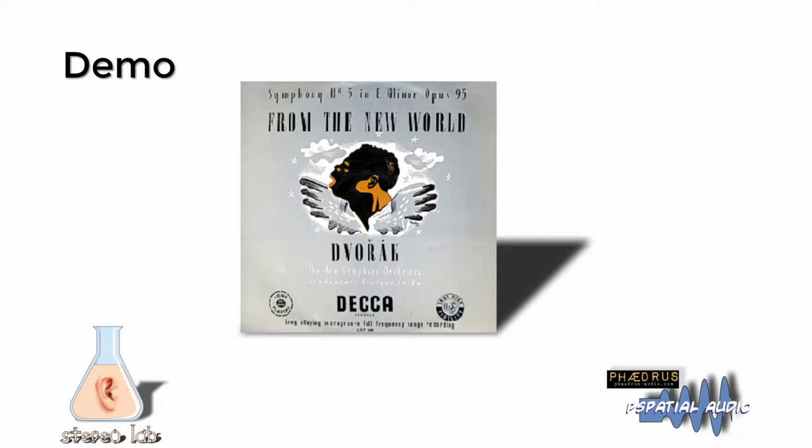So as an example, here we have a record made in the 1950s on Decca's then state-of-the-art FFRR system, which was what they used prior to RIAA equalisation. If RIAA is used to reproduce this disc, the bass is overboosted and the treble is muted.